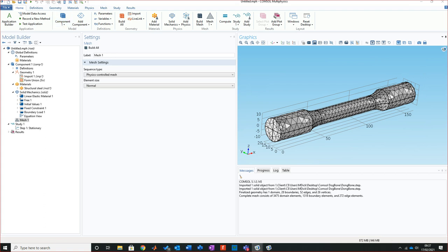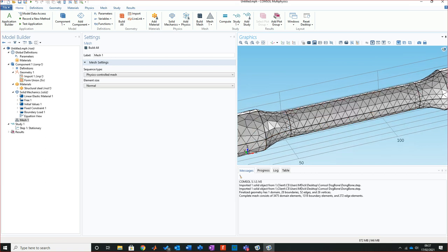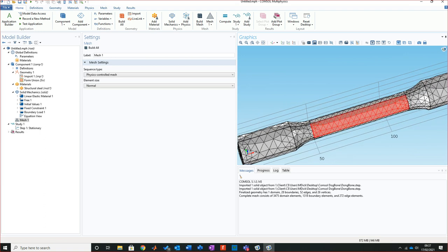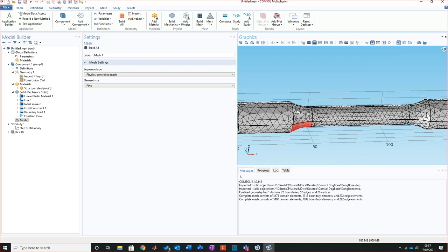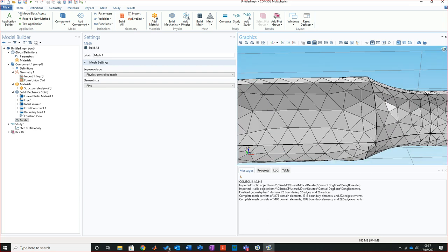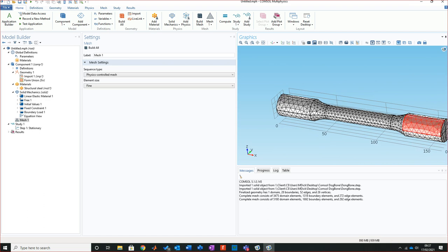I'll start. No. You've got to think this thing is moving longitudinally, so it's moving along that X component. If it's moving along that X component, that is no way any good. It's a tetrahedron, and it's made an entirely wrong assumption for me. So what I'll do is knock it down to something a little finer, because the size of it, that type of size is not a bad start as far as the sizing goes. What I'm referring to here is the actual distance between each node. It's not a bad start to give me a good assumption of what this will do under its extension.